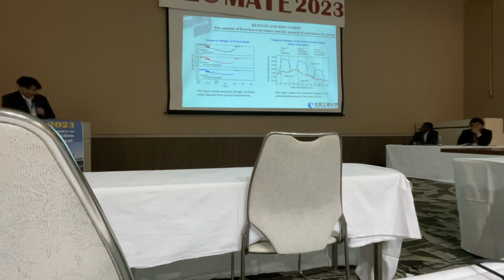So, results and discussions. In all cases, frozen depth reached 0.3 meter in early December 2022 and reached the surface course, and maximum frozen depth was reached between early and mid-February 2023, and frozen depth was deepest in case 1 and shallowest in case 3.